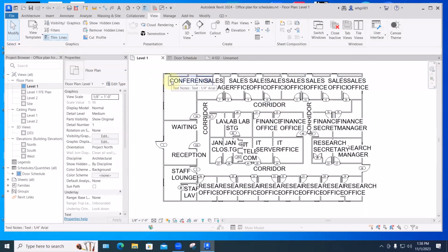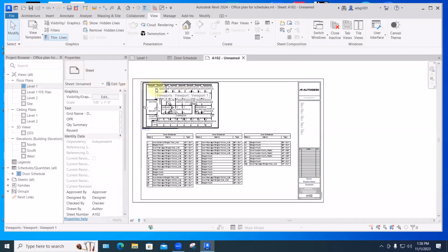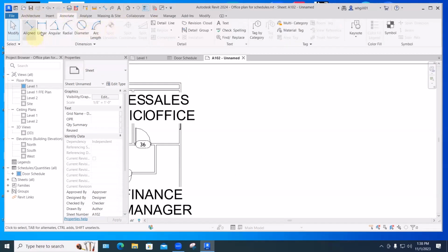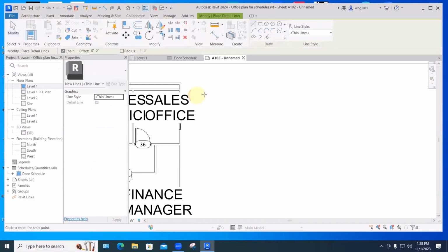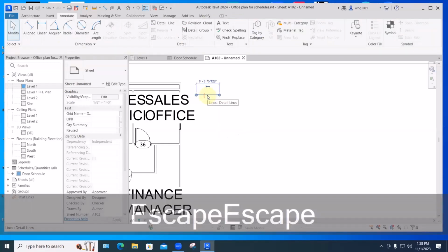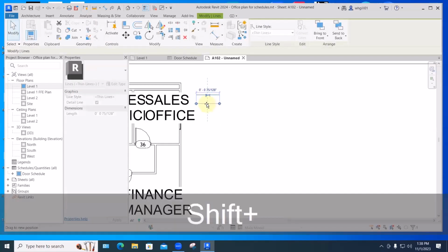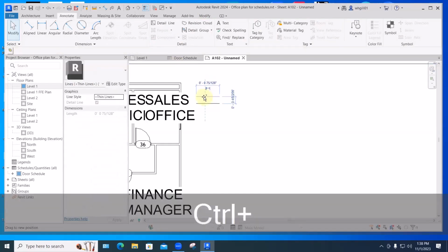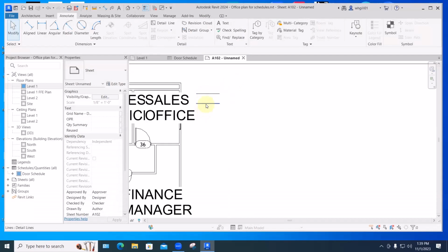Okay, now the reason that the text showed up so big once we had scaled this thing was that this font is 1/4 inch Arial, which means when plotted, it's going to be 1/4 inch high. So here we are where things are plotted. And if I just draw some lines first, let me just show you this. Draw a line here and copy it down to here. Sorry, copy, control, drag. We can see right away that text is 1/4 inch high plotted, which is what it's supposed to be.